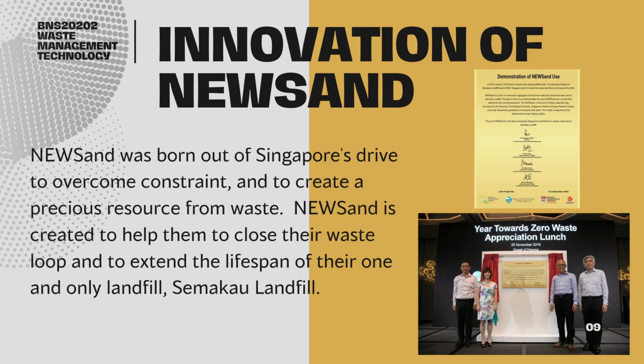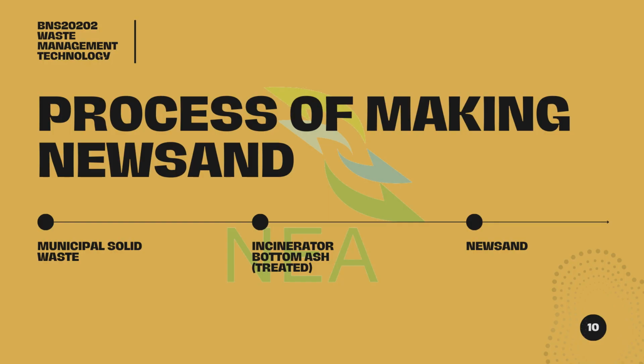Innovation of NEWSand. NEWSand was innovated due to Singapore's drive to overcome constraints and to create a precious resource from waste. NEWSand is created to help them close their waste loop and to extend the lifespan of their one and only landfill, Semakau landfill. Here is the process of making NEWSand. It starts with municipal solid waste. It is collected and goes through the incineration process where it is combusted, and IBA is the main solid output of the process. This IBA is then treated and used in the making of NEWSand.